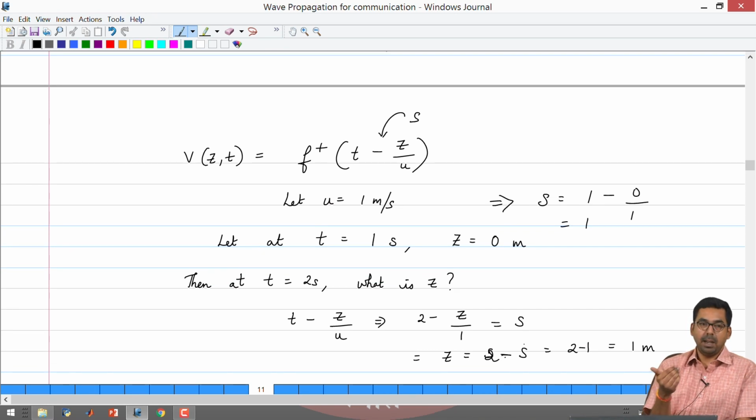So, it means that at any given point in your wire, there is a good possibility that you may end up with double the voltage, okay. This means that you will have to design the insulation between the top and the bottom layers of your PCB to be able to not break down with that voltage, all right, and the heat dissipation capacities of your lines have to be determined based upon these things.